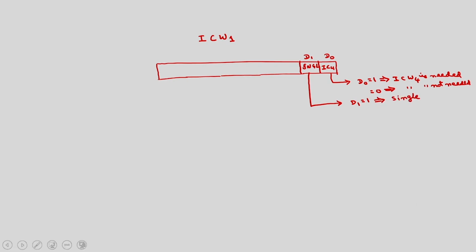As I have discussed, this 8259 can operate in single mode as well as cascaded mode. In single mode, 8 different devices can be connected to 8259, whereas in cascade, 64 devices can be connected. I will discuss how this 8259 will be cascaded to service 64 different IO devices.